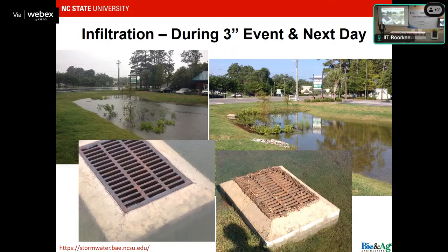Now, if it's 1.5 meters or 2 meters away, then you do have some infiltration options. If it's only a meter or certainly half a meter, then you're not going to infiltrate much water, maybe hardly any water.